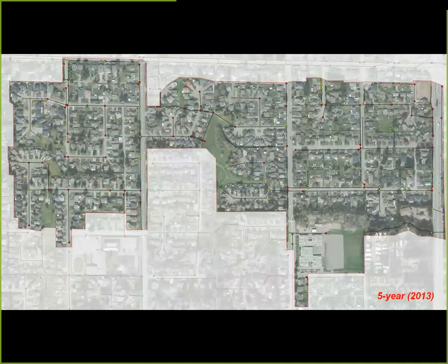Here's a picture, and it might be a little bit hard for people to see, but what I've got here is an air photo and a bit of an outline of where study area 1 is. There are some black lines in here that represent the stormwater system in terms of where it's located. And then there are some nodes that represent the manholes along these pipes. They're colored either yellow or green or red. The red dots are intended to represent flooding, or at least nodes that surcharge the surface. There's quite a few of those scattered around, and I'm hoping you can see them. They're probably at least 60 or 70% red.